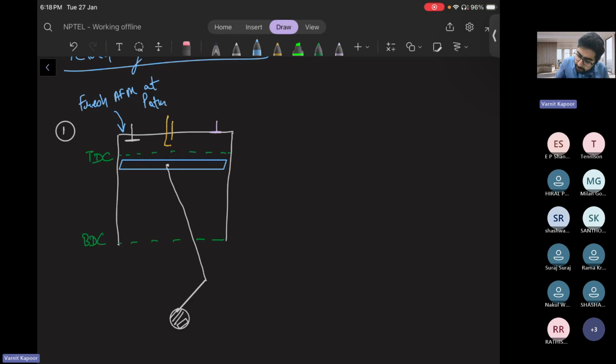So that means your pressure inside the cylinder is much less than P atmosphere. Okay, then only the fuel can enter. So this is your suction stroke. When the air fuel mixture enters, suction is being created and it draws such that the piston moves downward. Okay. So this is your suction stroke.